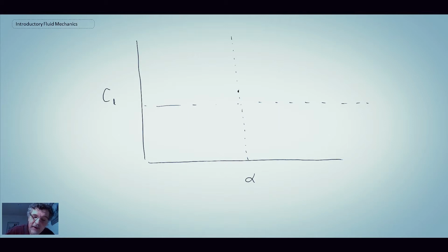If we were dealing with something like a NACA 0012 or a NACA 0015, a symmetric airfoil, where the first two numbers denote that it's symmetric, we would have the lift coefficient at 0 at alpha equals 0. So this is alpha equals 0 degrees.